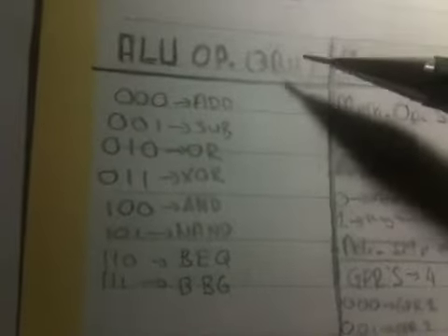Now, if we have given a branch here in the ALU operations, like these two, branch equal, branch bigger, if we have selected one of these in the ALU operations, then the value we enter here, this part, will be the line selection, and the other 3 won't be used.